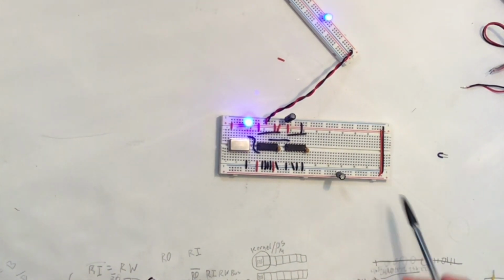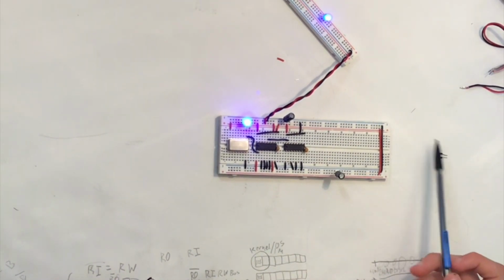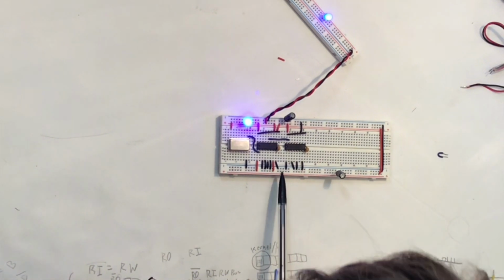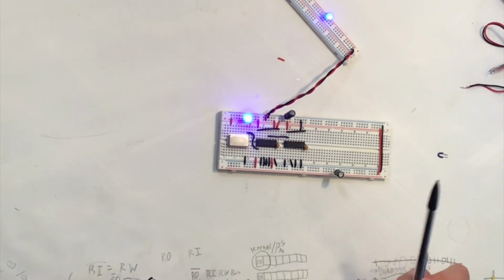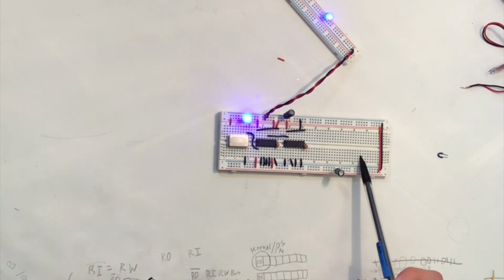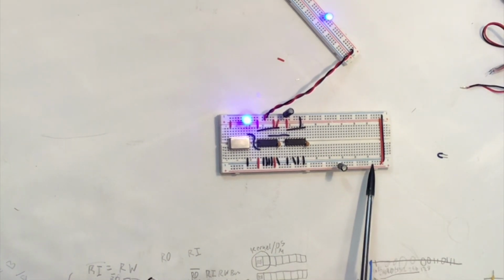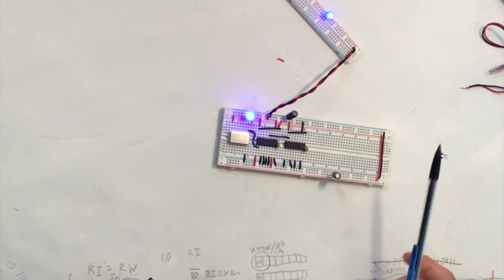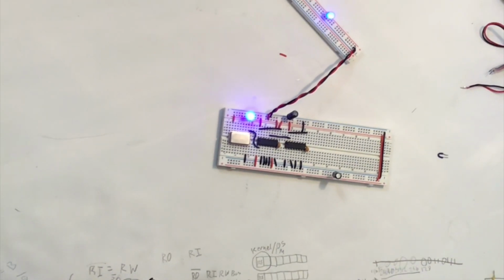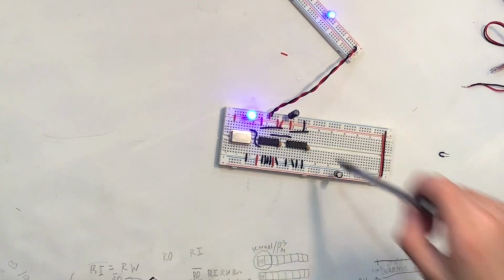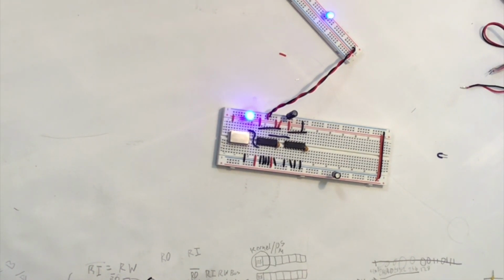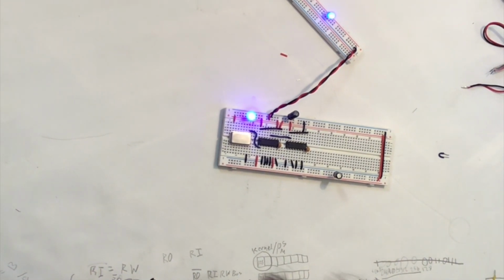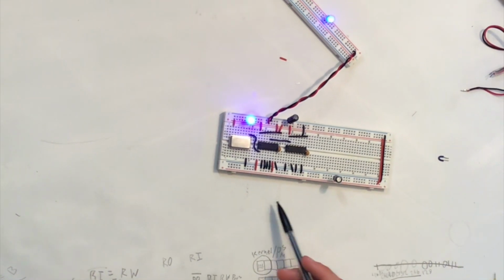So now let's talk about overclocking. Overclocking is theoretically possible. These chips often run a lot faster than their propagation delay time, however you say that word. So I think it's possible, especially if I was just using these chips, but I'm not. I'm using RAM that can take 50 to 70 nanoseconds to access, and you don't want to push that.